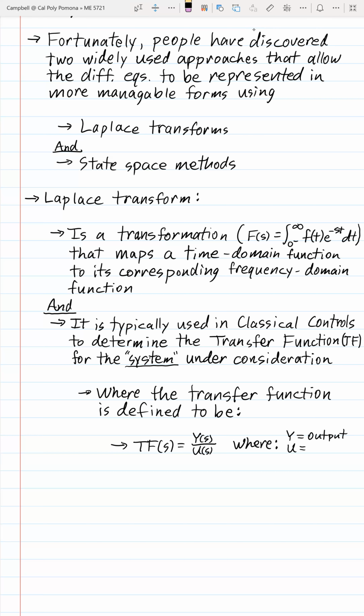So generally assuming one output for the system, and generally assuming one input for the system. Now, the key is that the input has to be a placeholder input. It can't be a specific input when we're talking about the transfer function. If you want to know the dynamic behavior of the system, then we will need to know the input, and then we can use that input to solve for the output function y of t once we know the input.